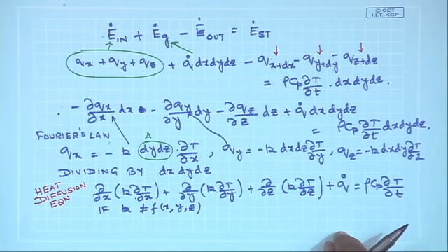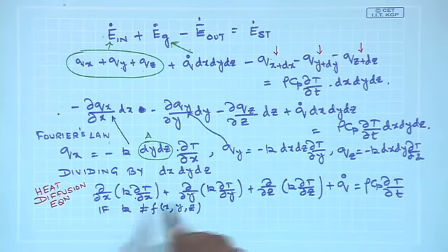which is true for many of the common systems that we deal with, but for some special crystals and so on, and especially when the system size is reduced, this k can be a function of the direction. But if we assume that it is an isotropic system, which many of the systems that we would deal with in our practical studies on heat transfer are, then this k can be taken out, it is not a function of x, y and z.